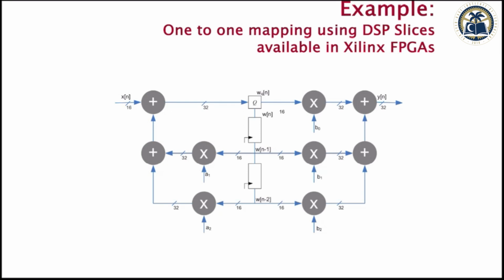Here is another example. If you look at this example, there is a big combinational path. You have to do multiplication, addition, addition. So there are three blocks; because of multiplication and addition, it may try to put a MAC there, but then there is another addition here, and another path which is this one.